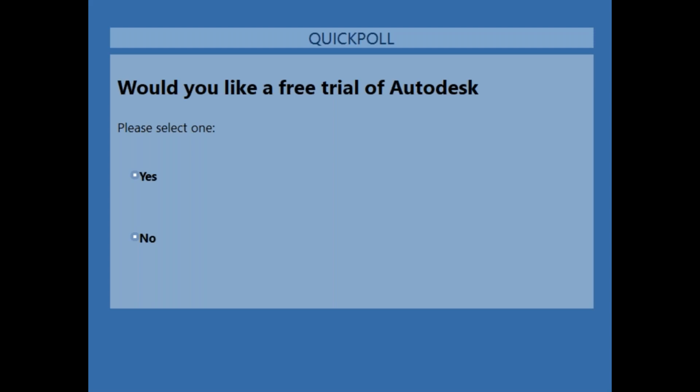Absolutely. There's another question that said, if I have a PDF file drawing, can I still do the takeoff for a curtain wall system? So you absolutely can still do whatever takeoff is needed within the 2D side of things. All you need to do is just upload that PDF directly into Autodesk Takeoff and start that traditional takeoff process that you'd be doing, whether that be in another takeoff solution or just in traditional methods with pen and paper. You'd just be evaluating that 2D drawing. Of course, if you had that 3D model, it's going to be even easier to take off that curtain wall system, but you can absolutely do so on the 2D side as well.